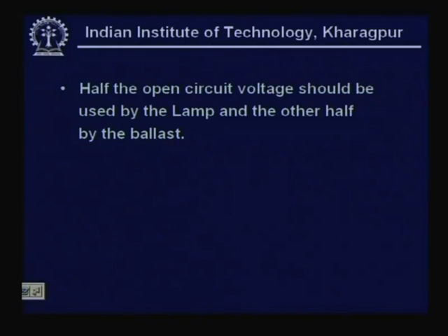Now, the issue is, we have already said, although discharge lamps radiate mostly by arc, they have two electrodes at either end, which, depending on the cycle of the AC sine wave, each act as a cathode, and hence each cathode is in turn heated by a filament which is similar to your incandescent lamp.